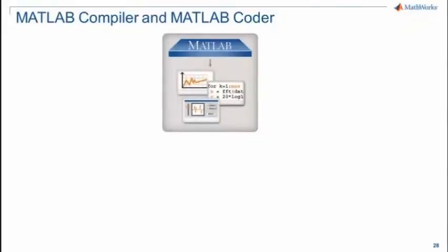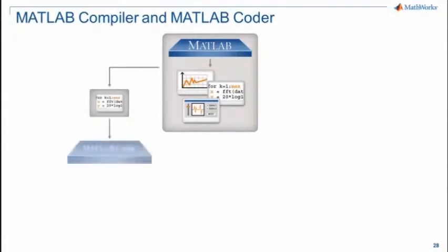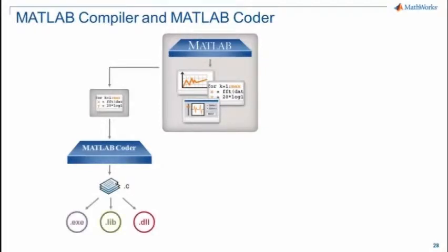If I take just the mathematical algorithm, then I can use MATLAB Coder to translate that MATLAB algorithm into C code. That gives me ANSI C code, the raw source, that I can then package up into DLLs, libraries, and executables.